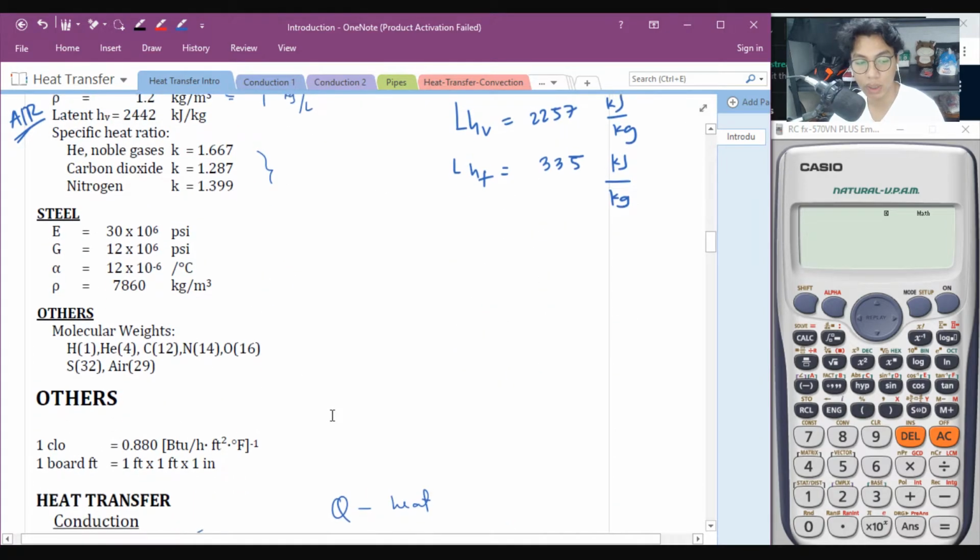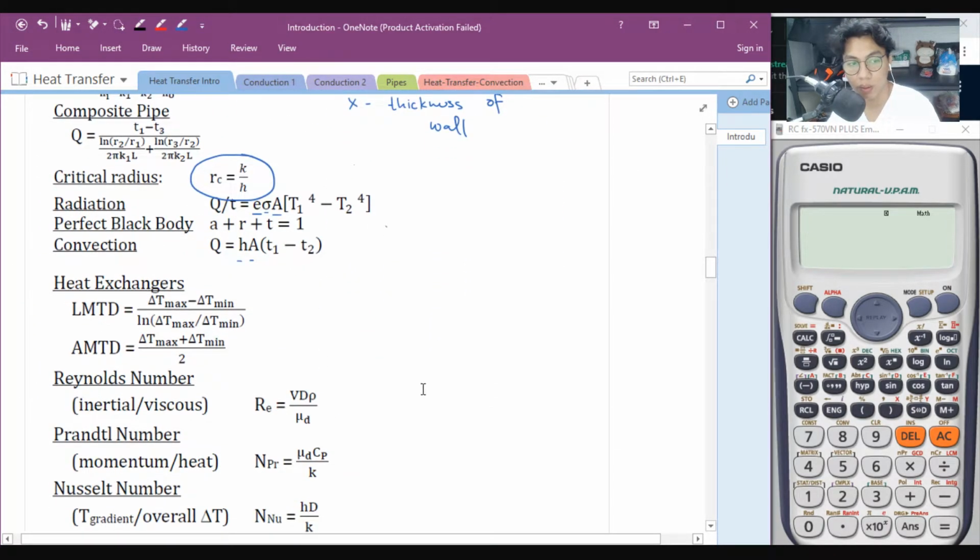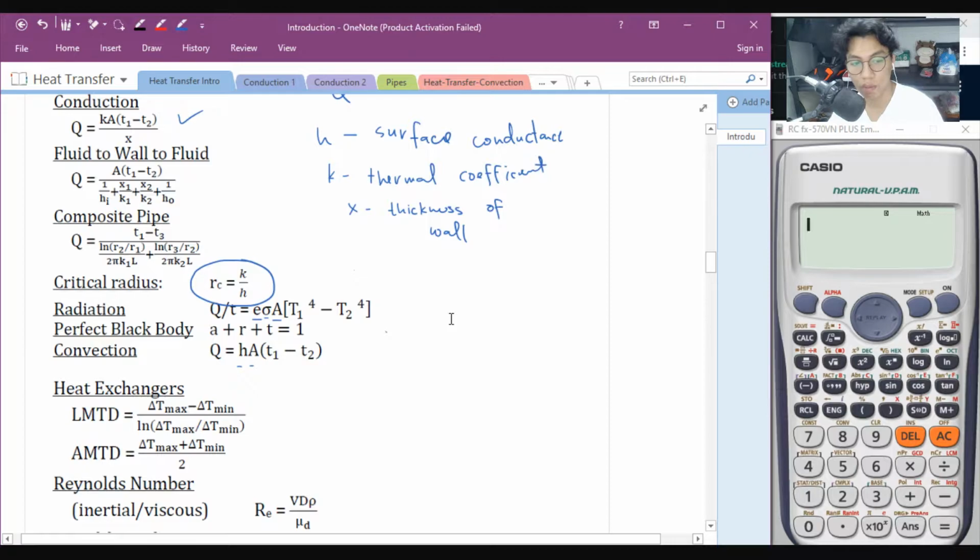Now, let's go with yung sinasabi kong convection. Okay, if the convective surface heat transfer is given by this formula, Q is equal to hAΔT, where A is the cross-sectional area of heat transfer and h is the surface film conductance of the fluid that is in contact with the material na magkakaroon sila ng heat transfer.